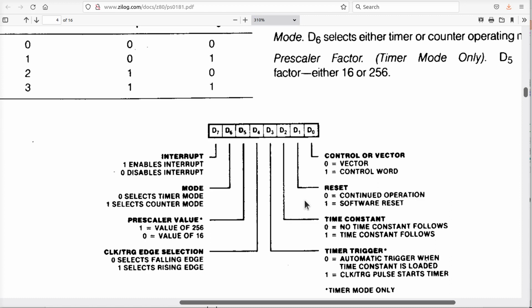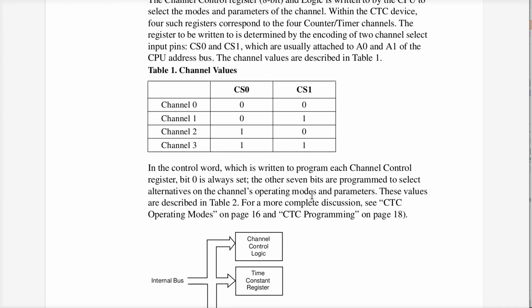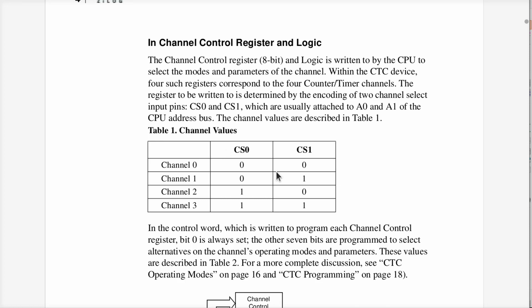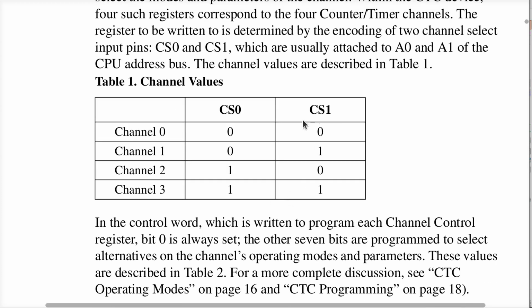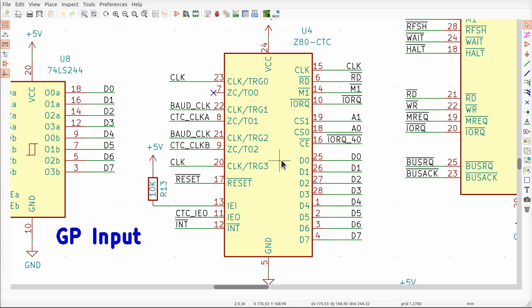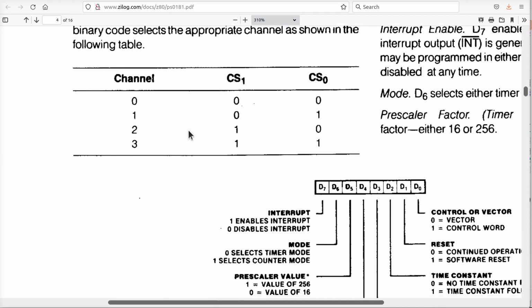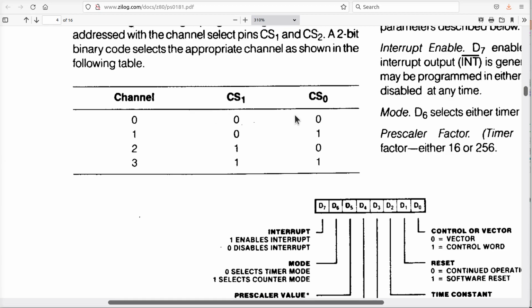Now, let's say you don't like reading old crappy manuals and you want to read the new one. Matters of the small things and matters of the big things. Someone decided that they know better than the entire rest of the universe, and they numbered these columns wrong. This, again, is our wonderful user guide from the art department rather than from the engineering department. This diagram is completely wrong. Channel 1 is when there's a 0 on CS1 and a 1 on CS0, as clearly drawn in this diagram on this page in this manual, which is correct. So basically they reversed these headings, okay?